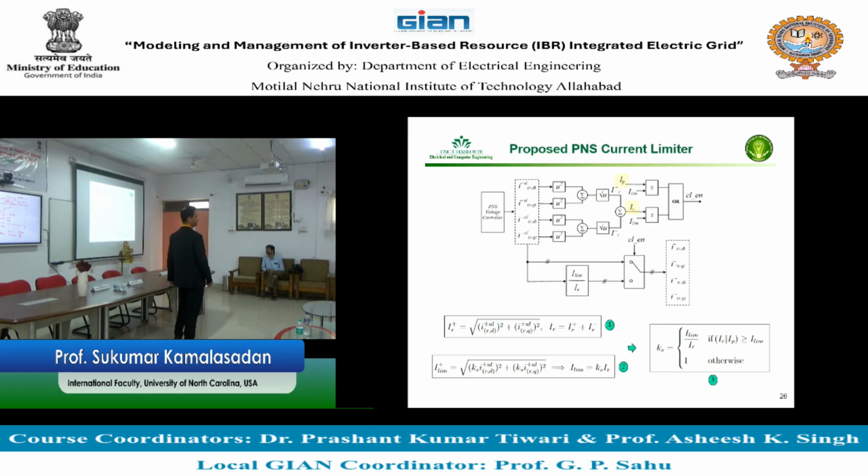This is another part that I am not able to discuss today, but when the inverter capacity is reached, you have to limit the current flowing out from the inverter, otherwise the inverter will blow. The problem with the inverter is that I cannot exceed it even for a short time. At that time, you will need to limit the current, and there are ways to limit the current by looking at the power current coming out from the inverter. When you limit the current, there is a challenge. The inverter you consider as a voltage source. As soon as you limit the current, it is no longer a voltage source.